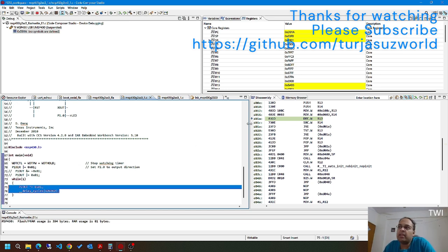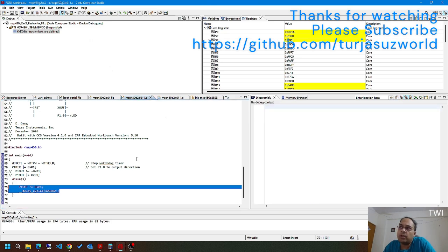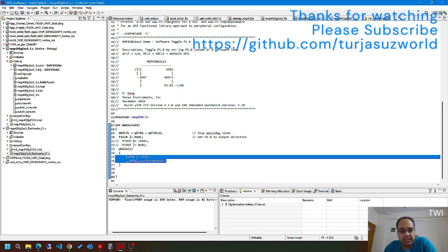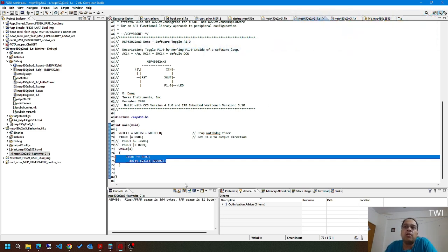So basically what is happening is you have updated your code using the TI-TXT file or the hex code which was generated from another project. This project helps you to fetch the text file from the internet. That particular interface is not here in this project. I will try to integrate it and give you another release of this code, wherein you can connect to a Wi-Fi network using ESP, download the code, do a CRC check on it, and then directly flash the code.